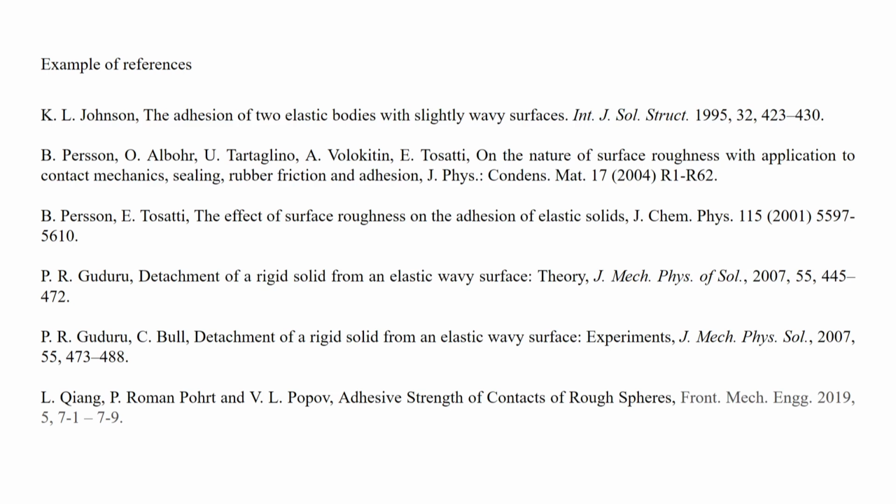Now this is quite an involved subject, this roughness of a surface and how it affects adhesion. Over the years there are several authors who have worked on different aspects of it, and they have described it in different ways. For example, Fuller and Tabor described the surface as having asperities, and then Johnson considers a slightly wavy surface, and then Guduru also considered an elastic wavy surface, basically a single wave or something like that. But the surface has not a single wave, it has several waves as we just described, and that randomness, or the hierarchical randomness, needs to be taken into consideration.